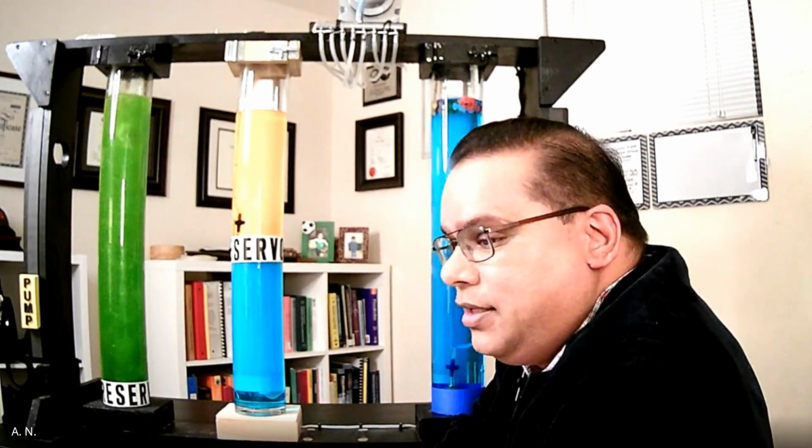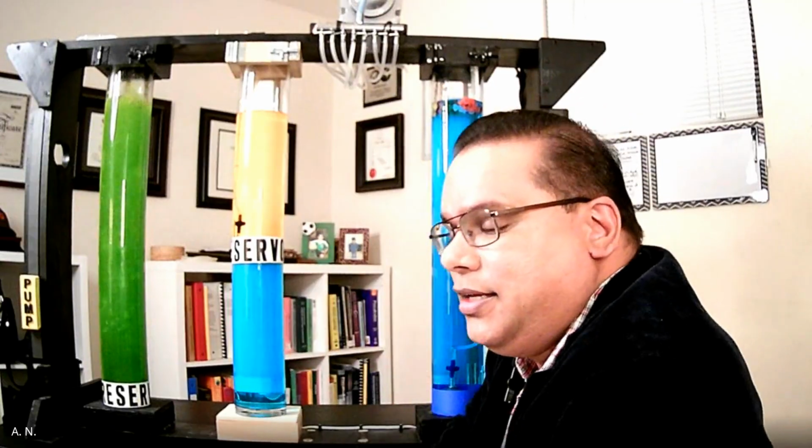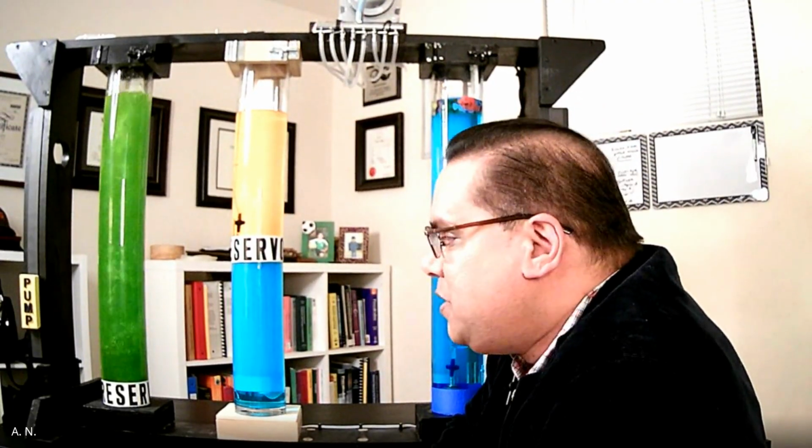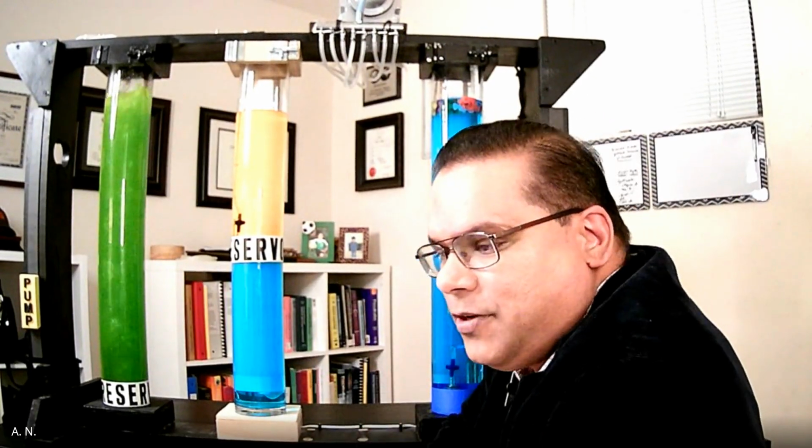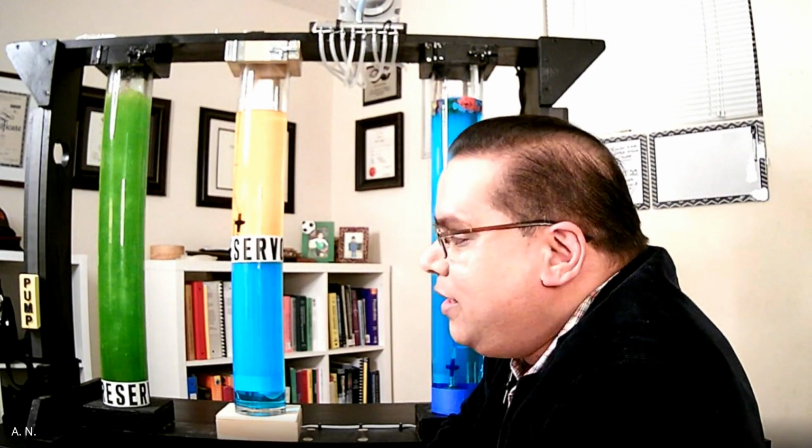You're going to have water. The water doesn't decide that it wants to stay. No, no, no. The density difference between oil and water is no way near the density difference between the gas and the oil and the gas and the water, right? So your water is going to go everywhere your oil is going to go.